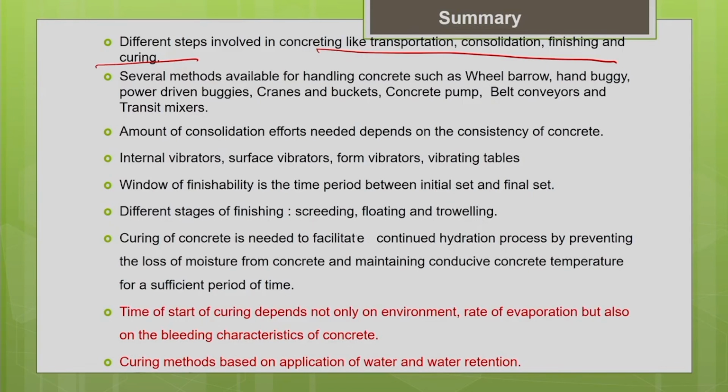There are many methods available for handling concrete. We have discussed simple methods like wheelbarrows and buggies, and advanced methods like pumping, belt conveyors, cranes and buckets, and transit mixers. The selection of the method you are going to use for handling concrete purely depends upon your productivity requirement.